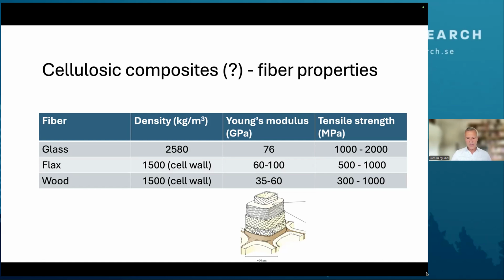And the main reason for that is actually that, first of all, we have the microfibril effect for plant fibers. If you look at the cell wall there below the Young's modulus column, the main S2 layer in wood has a certain microfibril angle. And if that angle is small, then we have the modulus approaching 60 gigapascal, especially if we also remove some lignin.